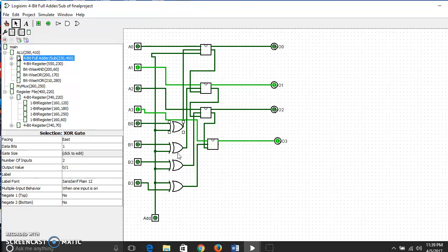Basically, the XOR gates perform the function of 2's complement. So it'll load the first number, it'll add 1, then perform the exclusive OR 4-bit on the second 4-bit number, which turns it into 2's complement, then adds it to the other number, and it performs the subtraction.